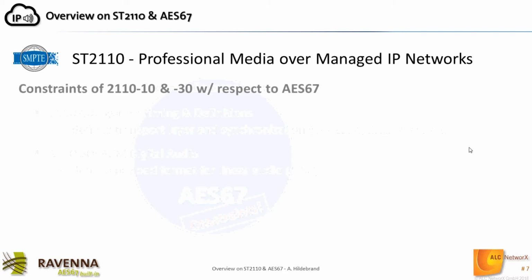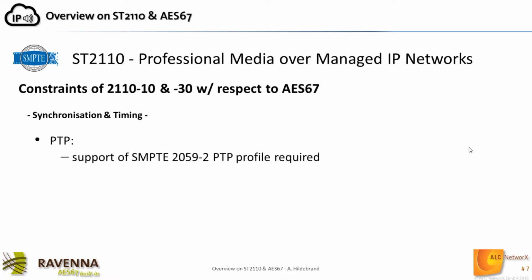First of all, we have 2 major constraints we need to be aware of when it comes to synchronization and timing. First of all, since SMPTE 2110 deals with video and is a SMPTE standard, of course, they require that their PTP profile, the 2059 standard, is supported by the devices. Now, luckily enough, since AES67 is also based on PTP, this is not too much of a deviating requirement for